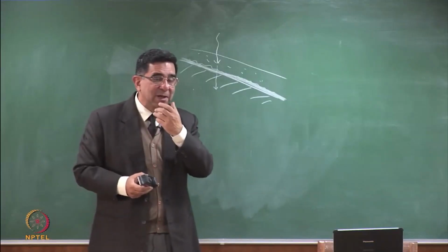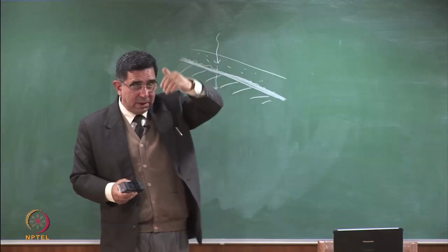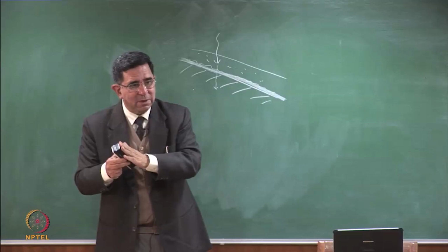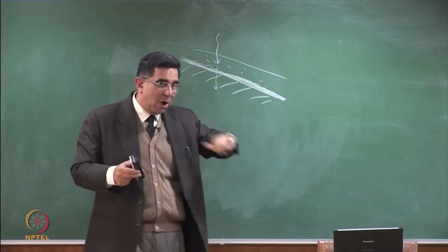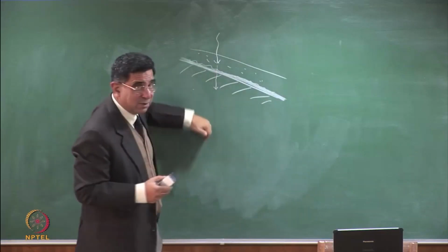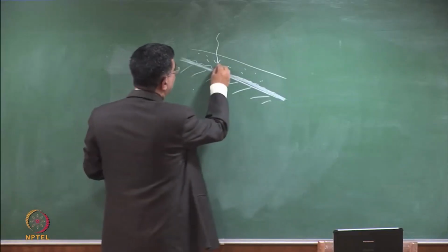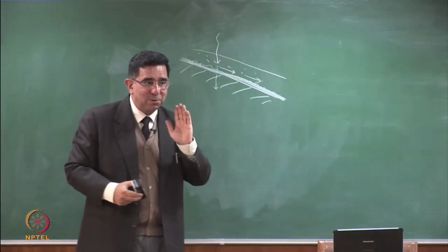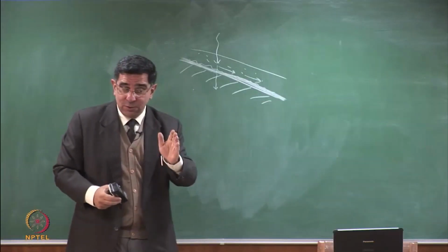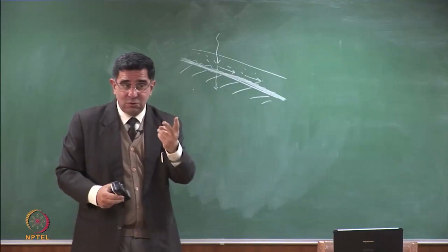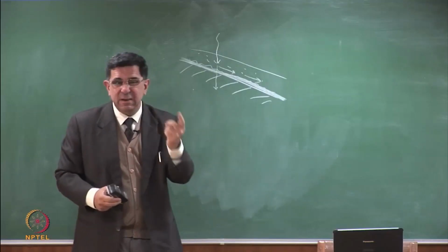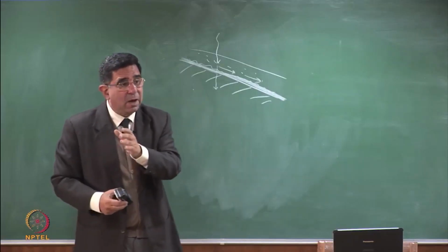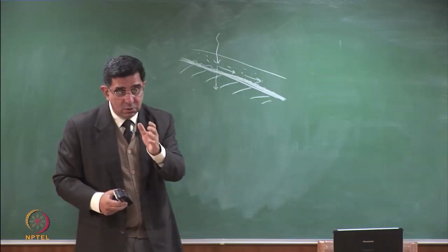So what happens in hilly regions? Rainfall is on the slope, water goes down. Where it hits rocks, what happens? It starts to flow along. At the moment, the seepage forces are downwards. But the moment it starts to flow like this, the seepage forces are downslope. It is destabilizing the whole thing, and that is the cause of instability. So two causes of instability: one, too many interfaces; two, flow occurring along the slope downwards. And this causes the slopes to be flat.